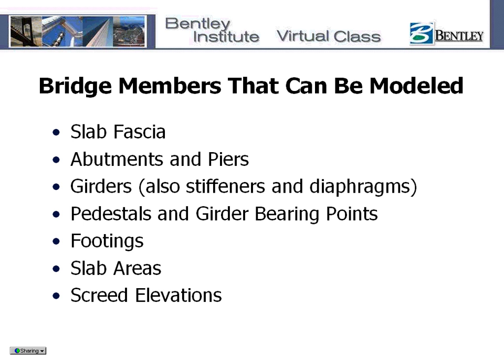InRoads Bridge has tools that allow you to lay out various members of the bridge. And here's a list of the ones that you can lay out, and we'll go through all these a little bit later during the demo. As you can see, you can lay out the slab fascia, which represents the edges of the bridge deck. There are also tools on reporting the slab fascia as well as edge of pavements.